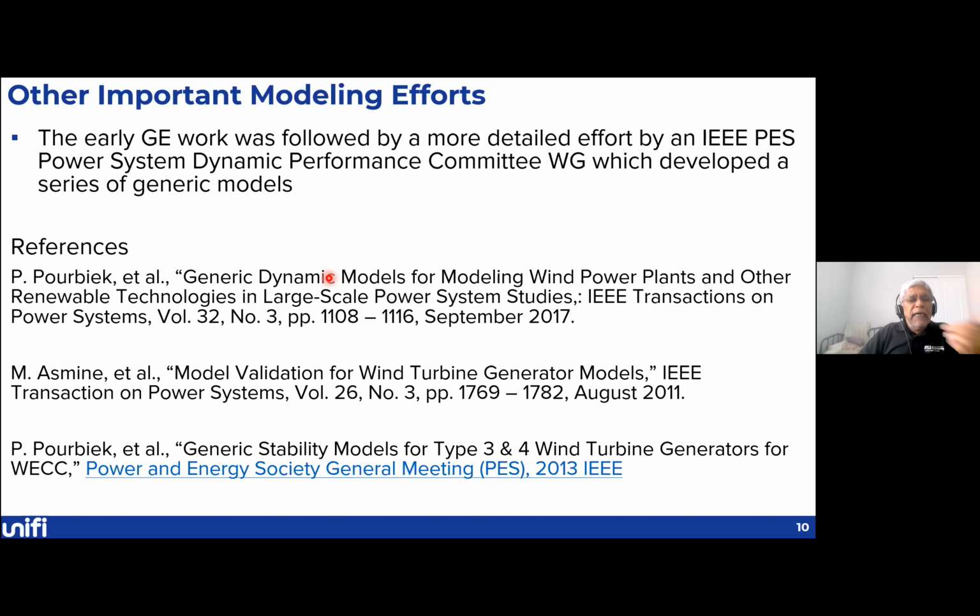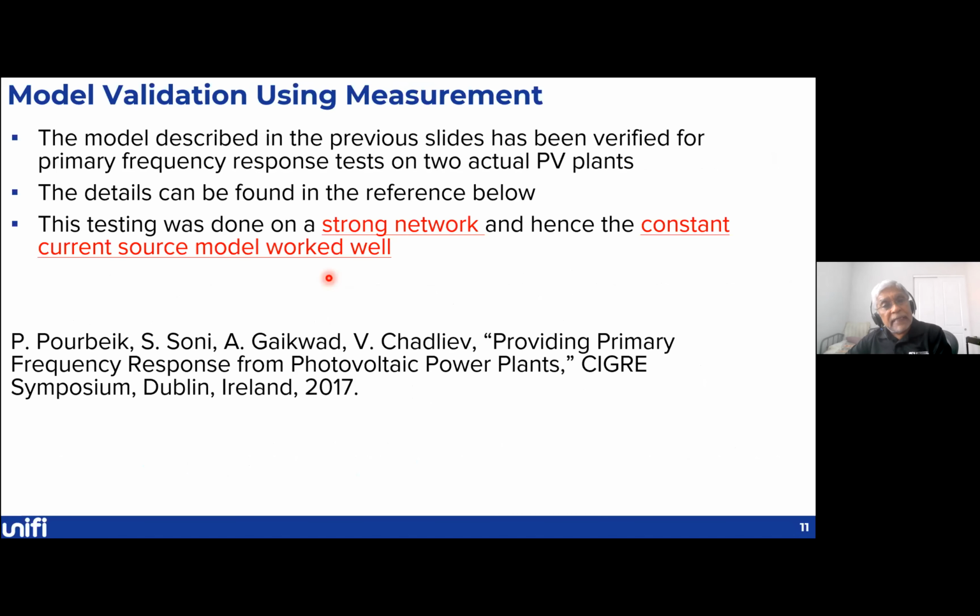Not everybody allows you to do these staged tests. So what people have done is looked at isolated portions of the system and then modeled that system in great detail using EMTP models, and then verified these positive sequence models in comparison with the performance of these detailed, well-accepted EMTP type of models. So that's another way of testing or validating some of these models.